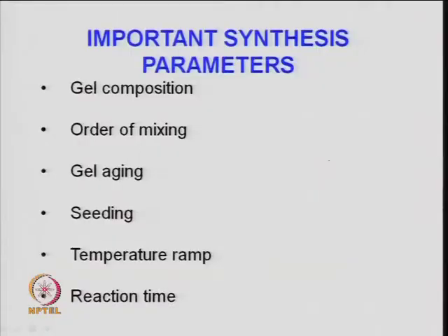So, an important synthesis parameter for zeolite production is the gel composition, which depends on the initial amount and type of the silicate and aluminate precursor, right. So, that is one: the composition of the gel, which will also depend on the hydroxyl ion added into the system for the reaction.